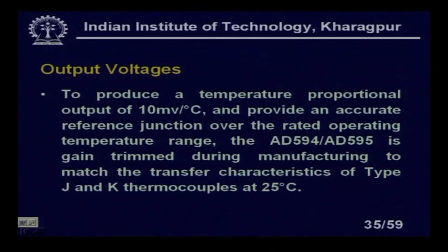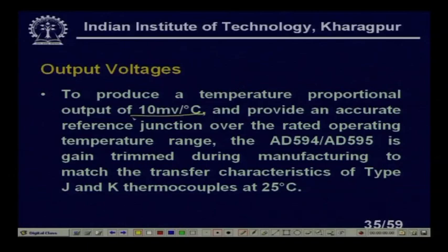But here you see at the output I am getting 10 millivolt per degree centigrade. So, sensitivity is extremely high, you can see here 10 millivolt per degree centigrade. This sensitivity is quite high. It is already signal processed and we are getting so much sensitivity here. So, the resolution obviously will increase.